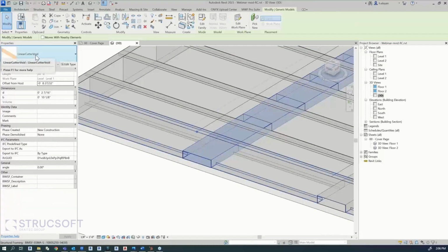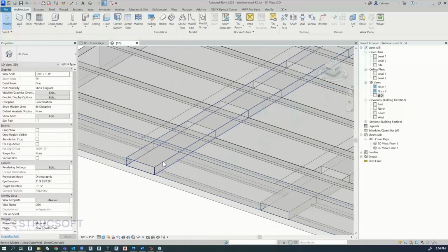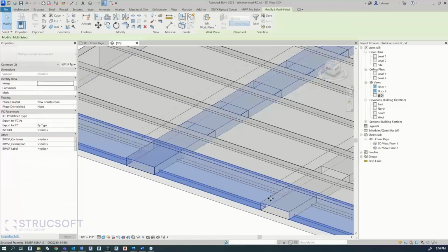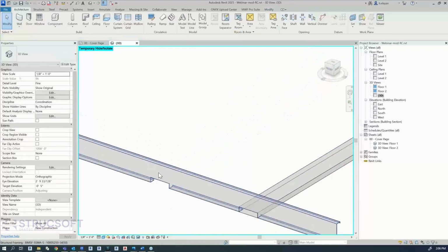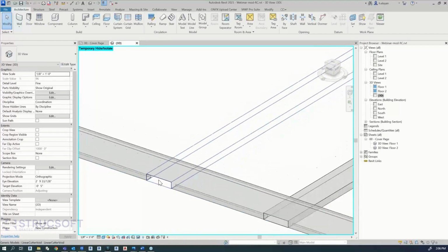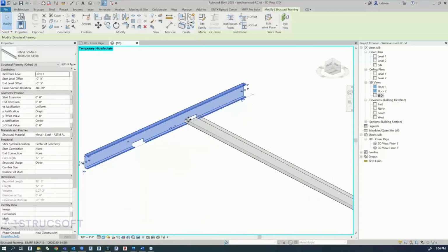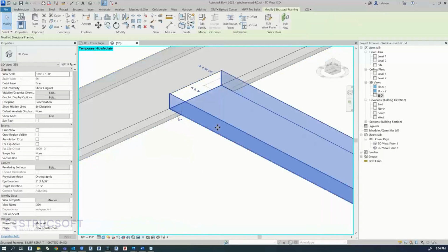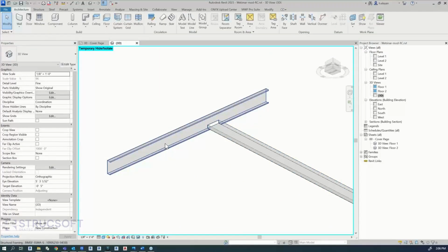Here you'll notice that I also have a void. So I've added a whole series with a rectangular void here. And I'm going to make a selection just to show these, and Tab and this, HI on my keyboard. Sorry, I didn't select this one, but actually this is a good opportunity to show that there's an opening right here. And let's take a look at this from the bottom. So this is what we're trying to achieve for today. If I delete this, look, it's going to delete the opening. I'm just going to bring it back.